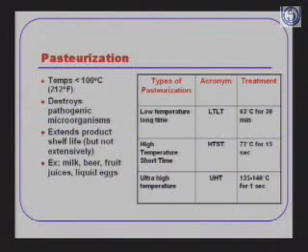The next degree of thermal processing is pasteurization. Pasteurization is generally done at a temperature below 100 degrees centigrade, and it destroys all the pathogenic microorganisms. Pathogenic means that they are disease causing microorganisms. But the pasteurization process will not lead to the extension of shelf life for a longer time. You have to refrigerate the pasteurized product always. You cannot keep it outside. So refrigeration has to be done along with the pasteurization process.